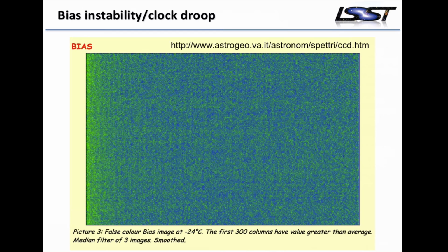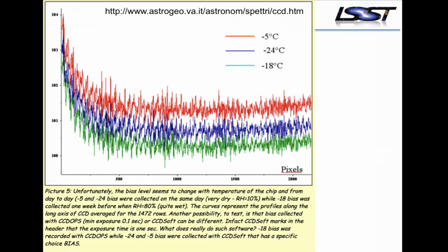Another way I've seen this happen is if the serial clocks are derived from voltage references that are not stable enough when you start clocking serially. If the serial clock rails start to droop, some of the signal in each pixel is actually fed through from the serial clocks, and that clock droop manifests itself as an apparent bias shift. And so these guys actually measured it as a function of temperature, and it's a non-trivial component that they'd have to deal with and eliminate.